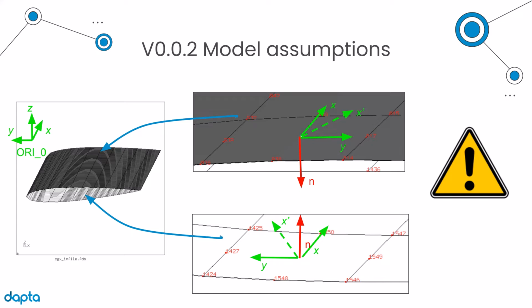That means that if we are rotating our main fiber direction by a certain angle on the top skin, it does rotate in the opposite direction on the bottom. And that means that we're never going to get this positive or negative bend twist coupling.